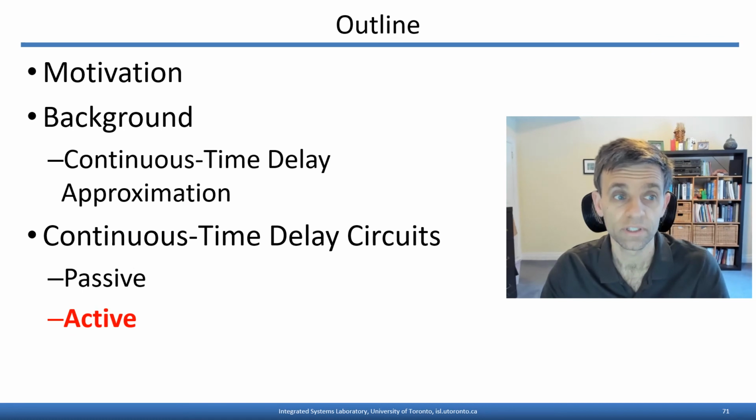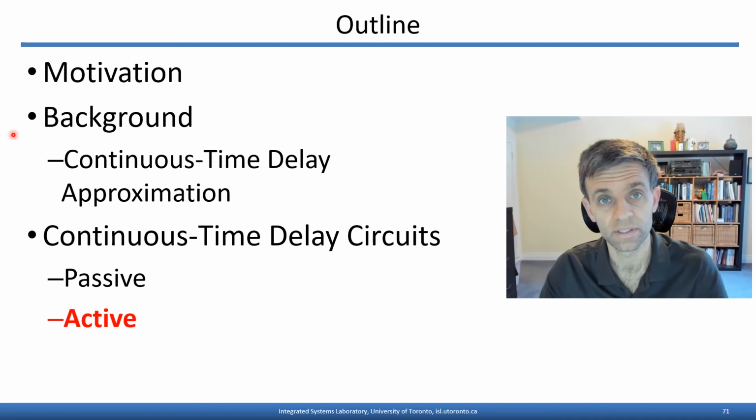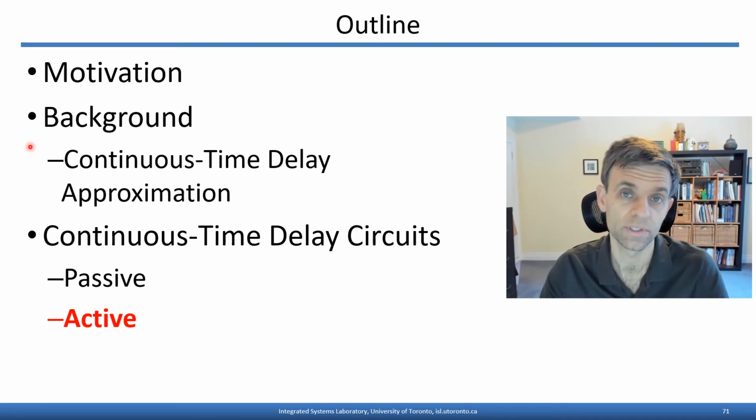So we've so far looked at the motivation and background for our interest in analog, continuous time, broadband, integrated delay circuits. We looked at some applications that were of interest: pipelining analog signal processing, FIR filtering, time interleaving, and we looked at their implementation using passive-only elements. And we saw that one of the main drawbacks with the passive elements is the fact that they use relatively large components, especially the inductors and/or transmission lines.